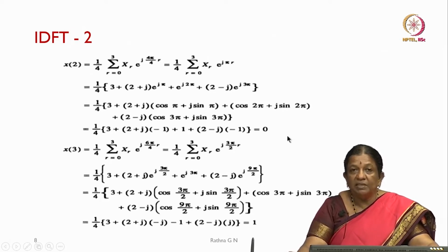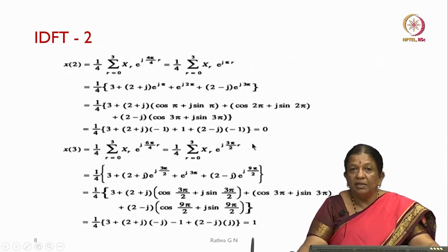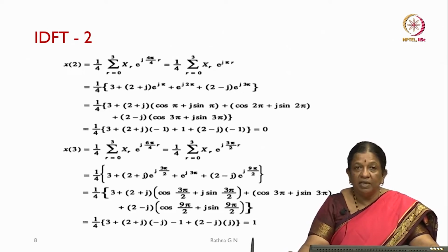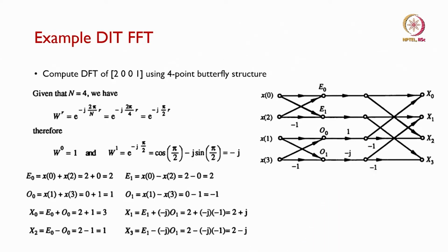So you will see that the original case was 2, 0, 0, 1, and that is the output. DFT is the analysis equation and IDFT is the synthesis. Whatever value you sent, you are getting back, so no compression is happening. Why am I calling it compression? Sometimes we use the DFT for compression also. We can eliminate some of the low values and use it in compression.